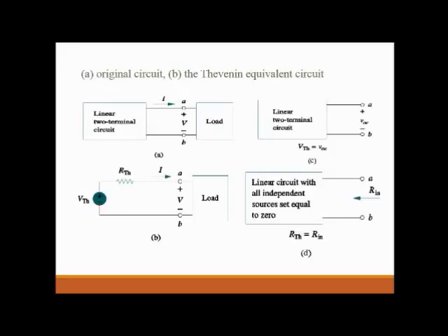You can go through the books for the processes of how to calculate these Thevenin circuits. You have to consider one side as open circuit, then you have to calculate the net resistance looking through that open circuit side, and finally you can get RTH, VTH and so on. You can proceed. We will have a video on Thevenin's and Norton's theorem afterwards. As the basics of these theorems, you just need to learn this.